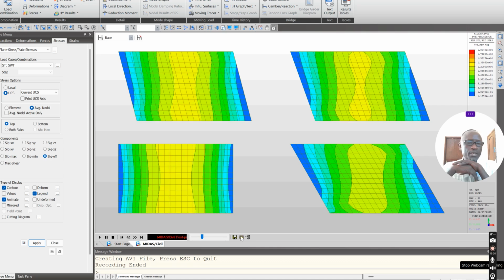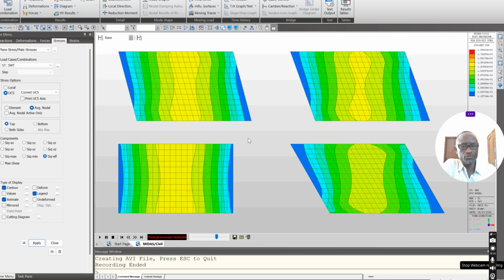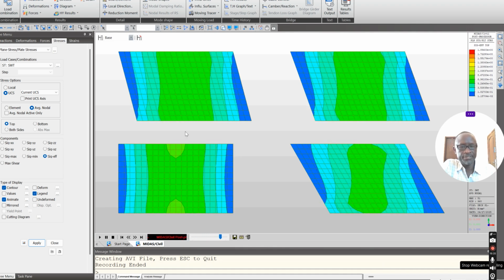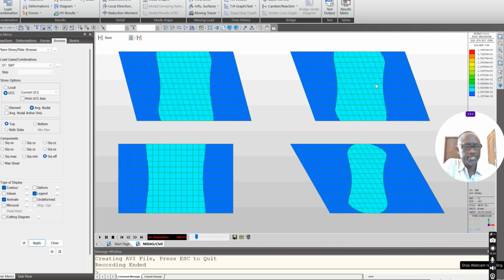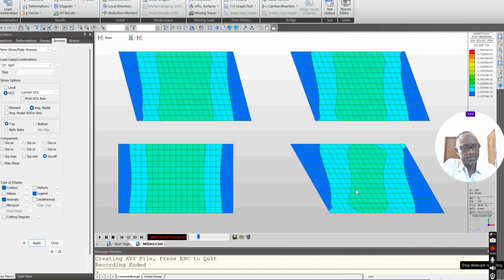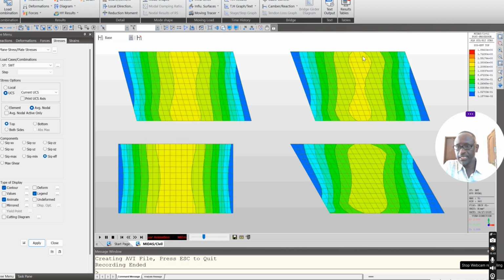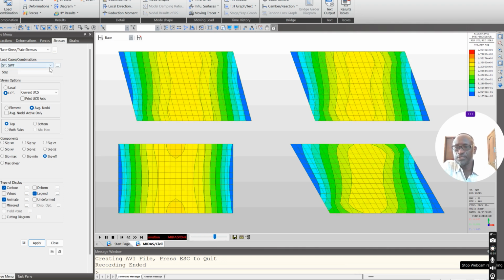So this is just an animation, just to show how the stresses get distributed on the normal deck slab, the 90 degree, to a 15 degrees skew angle, to further degrees of 20, and then on this one. That also helps because I told you there is twisting, there is moment, there is shear, axial load. So this is due to self weight.